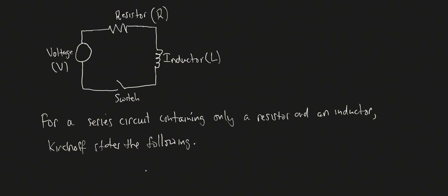The general principle, in fact, not just for these types but for many types of circuits, is that Kirchhoff says the voltage drop that occurs across each component, again, the resistor would be a component, the inductor would be a component, if you sum up those voltage drops, it has to be equal to your impressed voltage. That's basically what Kirchhoff says.